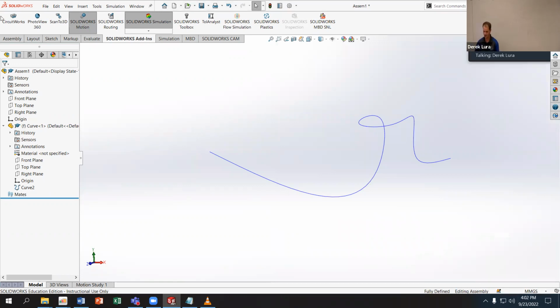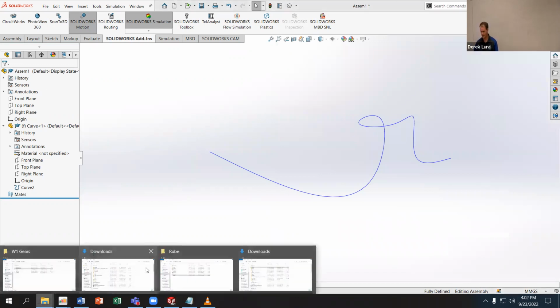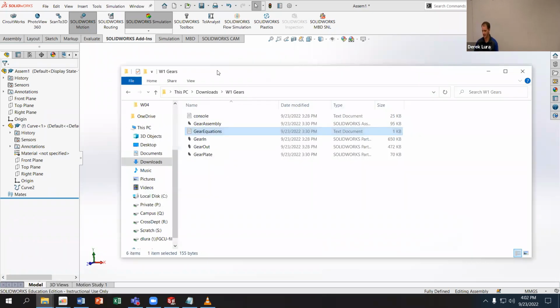I've got these parts in here. I'm going to go and load in the head because it seems like that's going to define the position of the rest of the parts. And I think one of the things that can be important about doing this is when you have parts that have a lot of motion, trying to get all of the parts sufficiently defined as you're going through it can help save you a lot of headache.